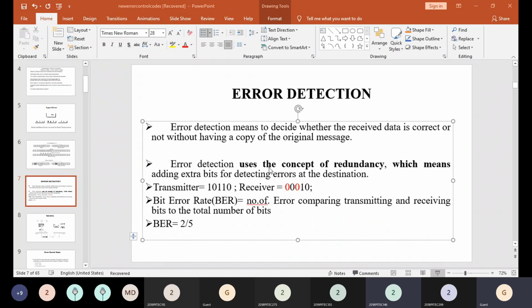If you look into the block diagram based representation, m bits are considered as the message vector here. Then you have the generator polynomial. When you multiply m into g, it becomes the code word.